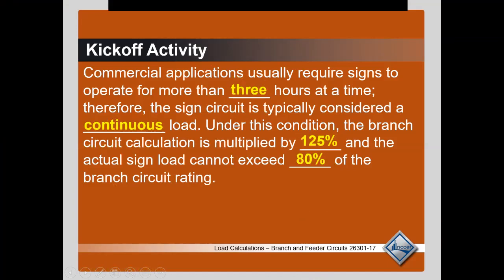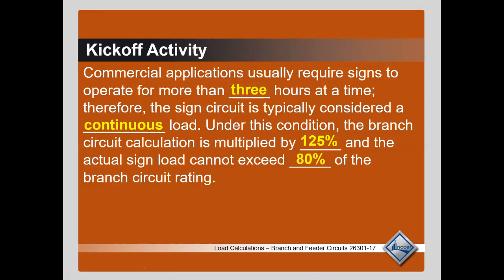All right, commercial applications usually require signs to operate for more than 3 hours at a time. Therefore, the sign circuit is typically considered continuous load. Under this condition, the branch circuit calculation is multiplied by 125%, and the sign load cannot exceed 80% of the branch circuit rating.